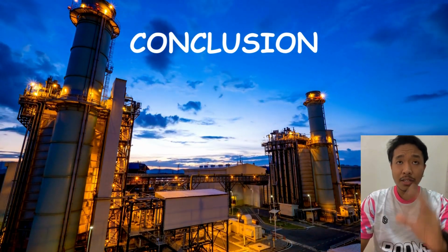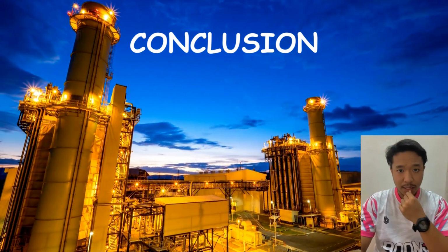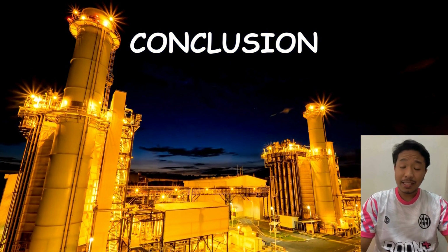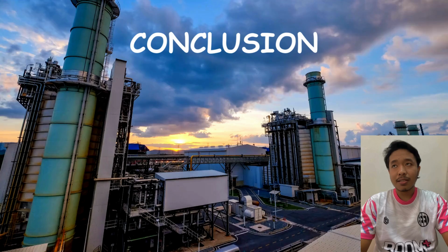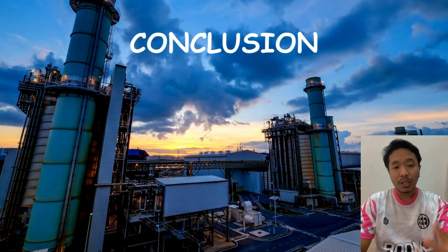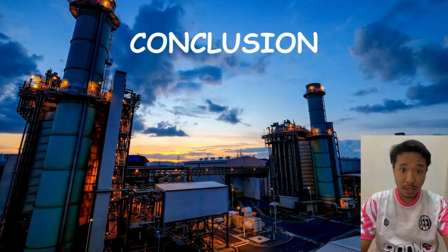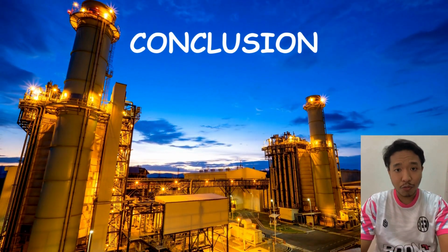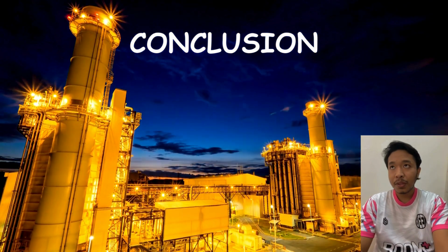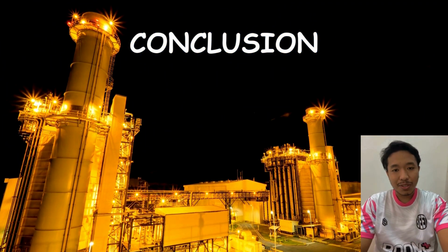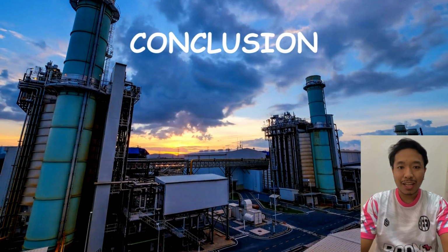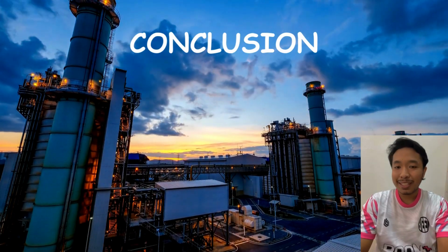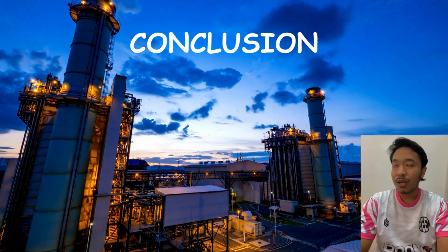Condensers are essential in power plants, especially in the Rankine cycle, as they turn steam into water, maintain low turbine pressure, and improve efficiency. There are two main types. The first is the direct contact condenser, where steam mixes with cooling water.